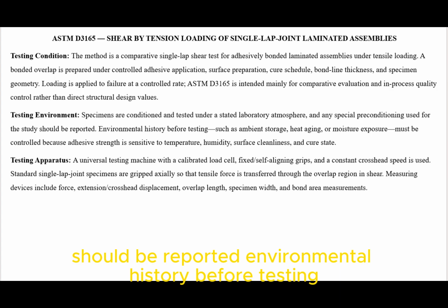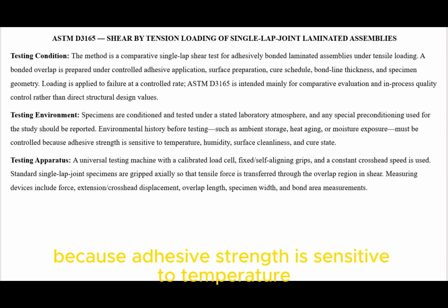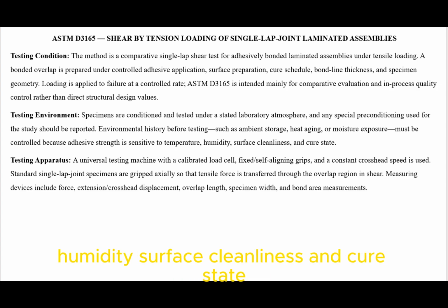Environmental history before testing, such as ambient storage, heat aging, or moisture exposure, must be controlled because adhesive strength is sensitive to temperature, humidity, surface cleanliness, and cure state.